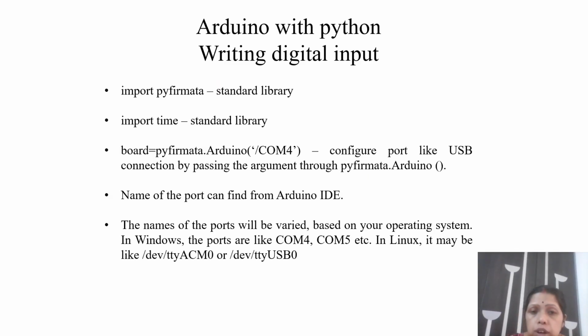Now, after installing the PyFirmata or standard Firmata library, you have to write this set of instructions. Suppose I discuss Arduino with Python with writing the digital output. Import pyfirmata, this is the standard library for Firmata. Import time. Import time is required.